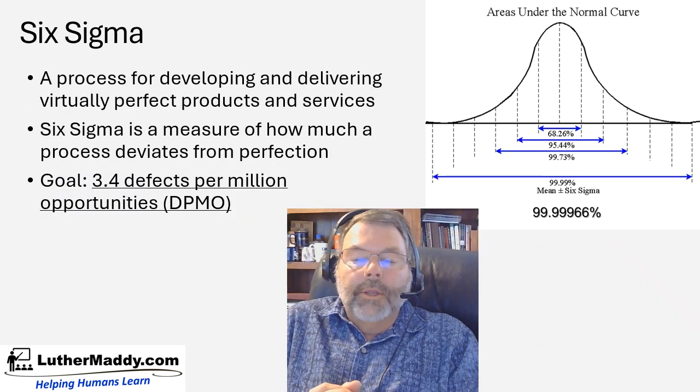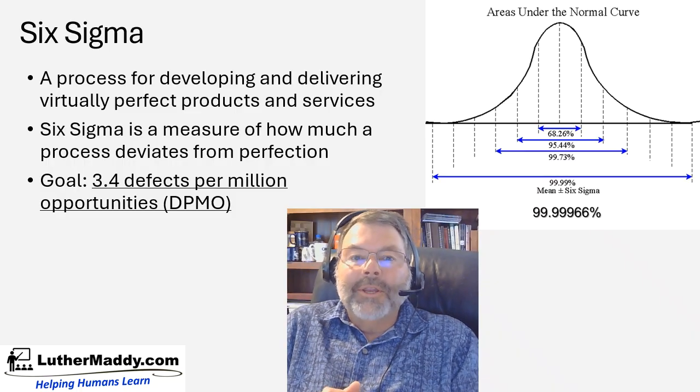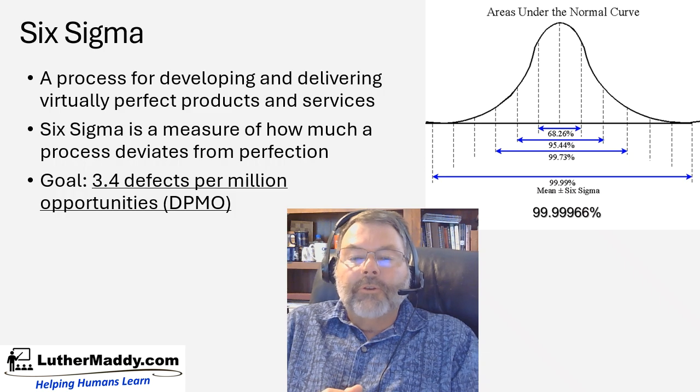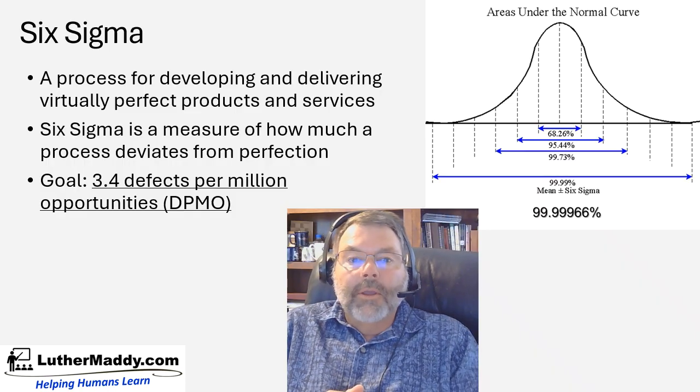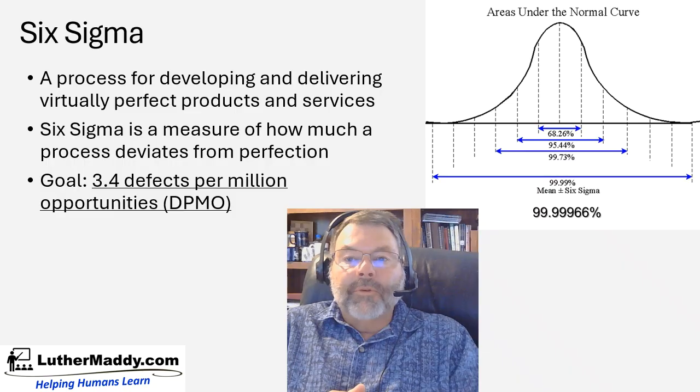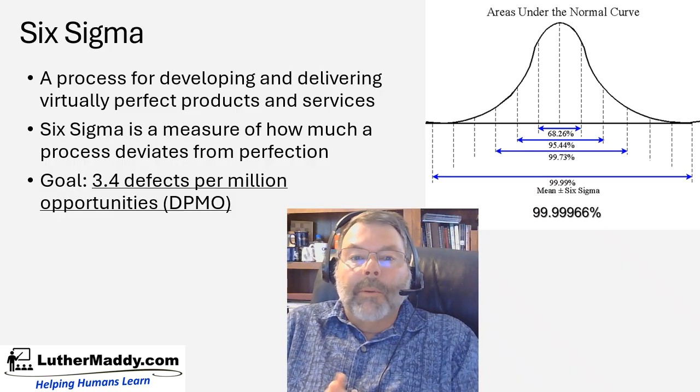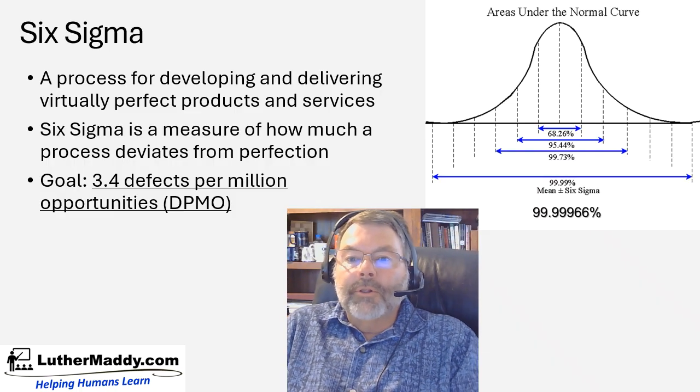As you study quality control, either at this level or at a deeper level, you will encounter the term Six Sigma. Now, Six Sigma is a complete process of quality control, but let's just talk about what it means from a basic standpoint here. Sigma represents a standard deviation. And you have an example of a normal curve here, and you remember from your statistics class that plus or minus 3 standard deviations includes 99.73% of all of the occurrences under the curve.